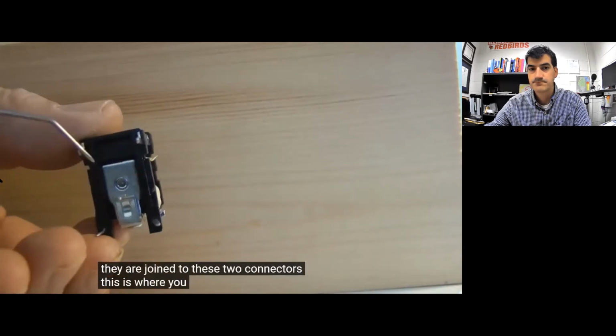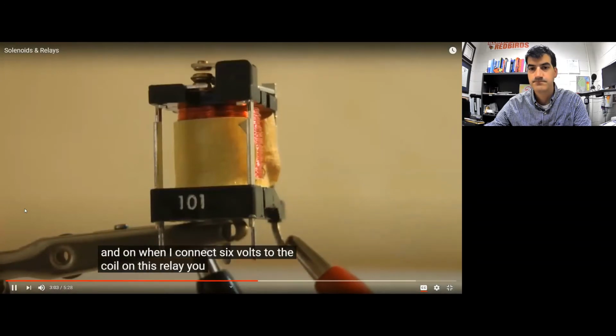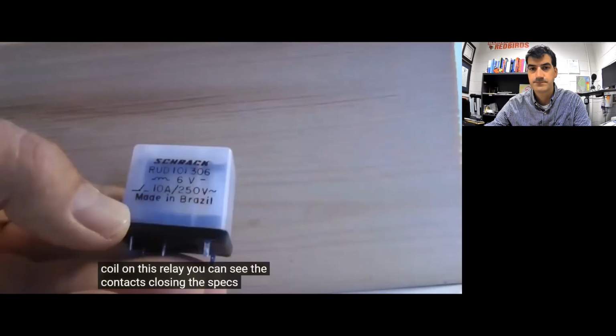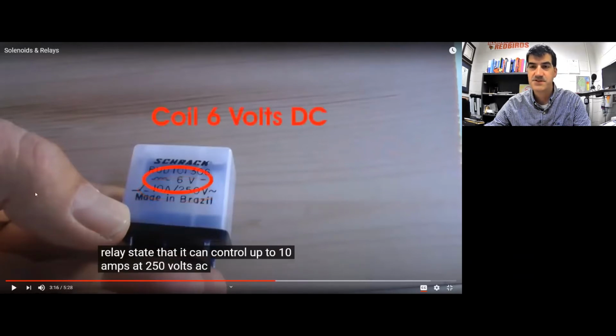This is where you would connect a circuit. The contacts would switch it off and on. When I connect 6 volts to the coil on this relay, you can see the contacts closing. The specs for this relay state that it can control up to 10 amps at 250 volts AC. All right, I think I'll stop it there.